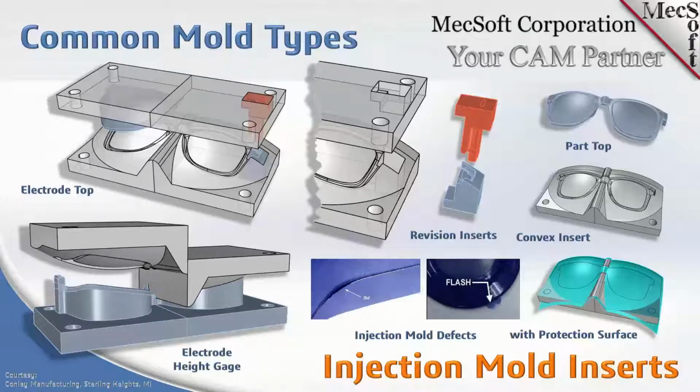You will have a prototype mold, with which you create some prototype parts. Your engineering customer will review those parts. They'll make changes. They'll take the parts and mark them up. They'll actually take a marker and write on the part. Say, I want more material here. I want less material there. We need to make revisions. So the mold maker will make sets of inserts. He's probably going to machine at least 2 sets and possibly even more, just for that purpose, for revisions and whatnot.